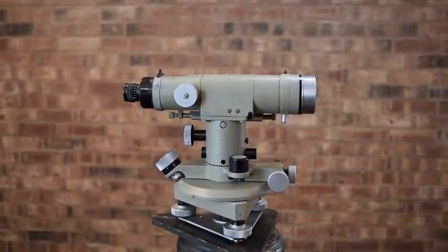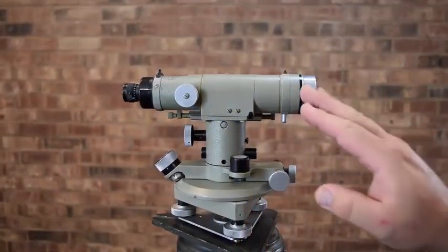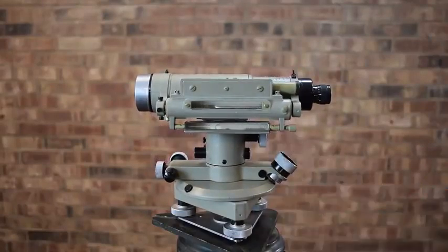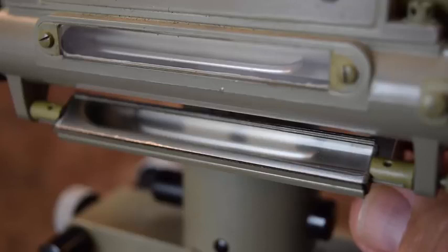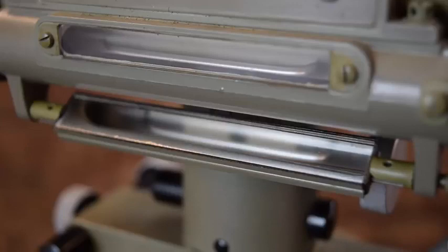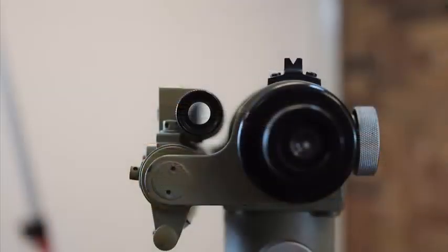The tilting level represented the next generation of leveling precision. This one was manufactured in the 1940s. As optical science had improved, it sported a shorter telescope and it had an innovative feature that allowed more precise leveling, the split bubble. Below the long bubble tube, an adjustable mirror reflects light into the fluid and bubble in the cylindrical tube. Using a separate eyepiece and another internal mirror, the operator views two halves of the bubble image and adjusts the level carefully to align the two images.